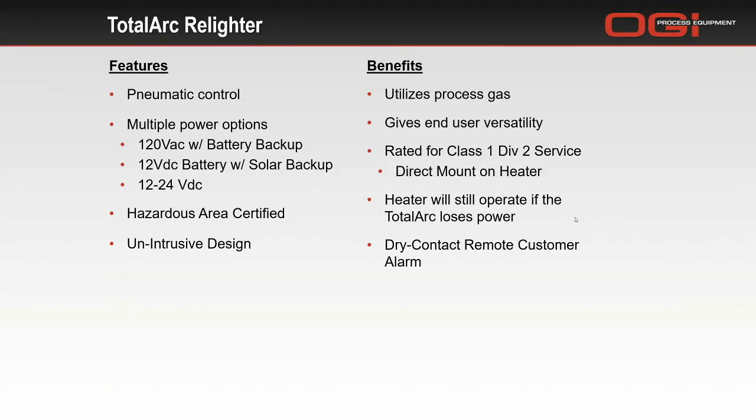So those areas that get quite a bit of snow coverage, we almost request that once a week someone go by and make sure that the solar panel is still exposed. Additionally, we also have another TotalArc Relighter that has a power option of 12 to 24 volts DC. This was created based on the request of a few customers that actually have power on site. And in some of these facilities, they have 24 volts DC that already comes from a system that is under battery power.